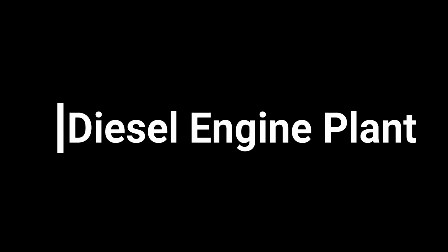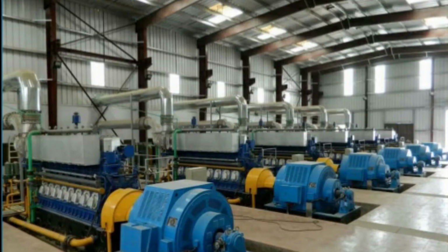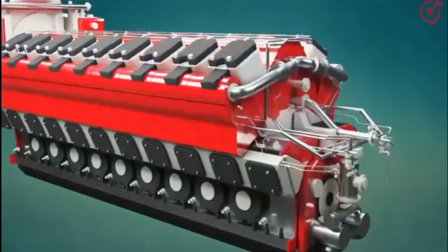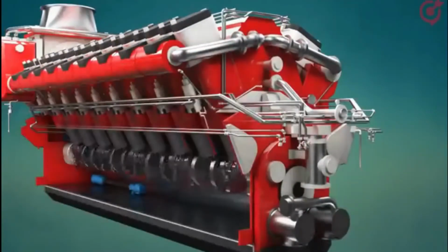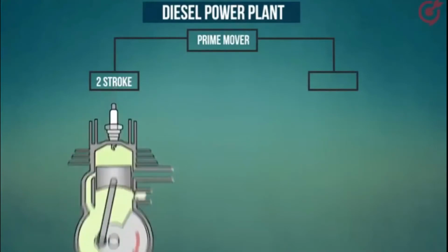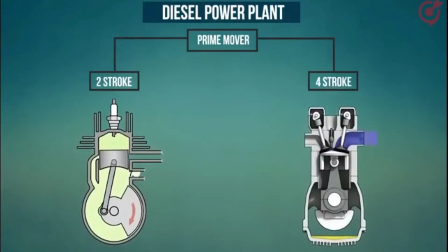Diesel engine plants are usually built for remote communities and ships. The plants usually operate as base load generation, 24 hours a day, to supply power to industrial facilities, the camp, or villages. The engines for base load are of slow speed, 400 to 900 RPM type, operated on continuous duty.